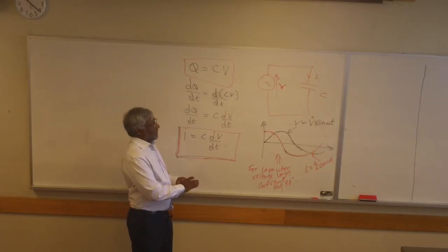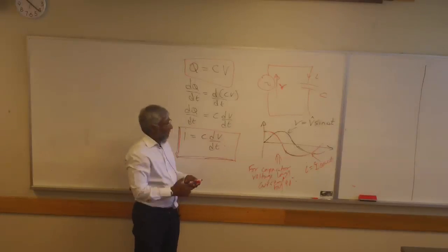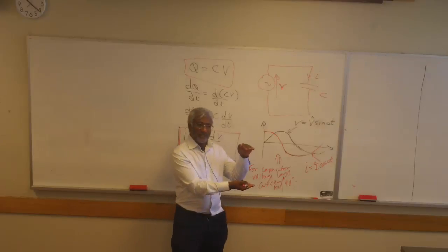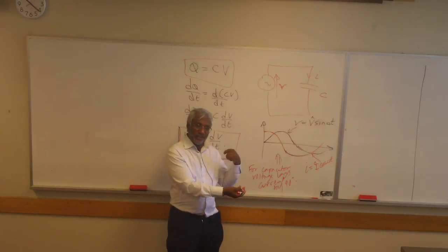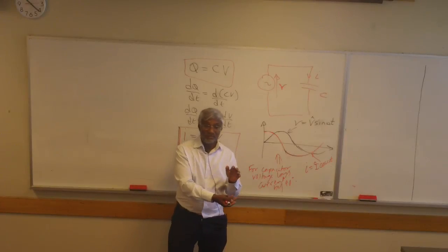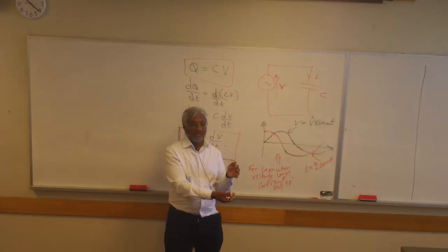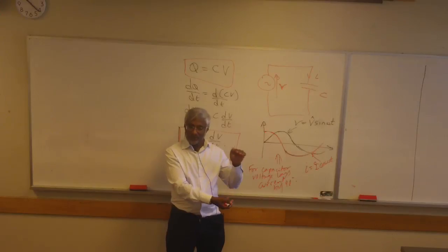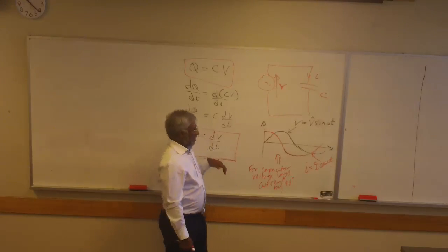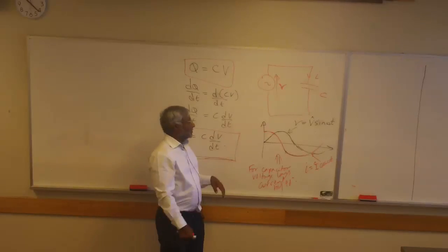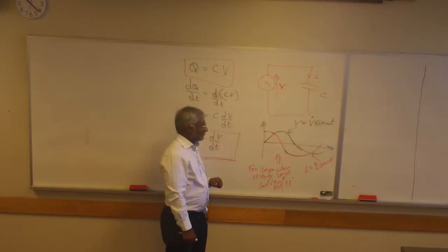That is obvious if you think about it. If you have a capacitor with voltage across it, then it means sometime in the past, current must have gone into it. So you don't have to read 25 books and worry about it. It is obvious that for a capacitor, current has to come first before it can be charged with voltage. So therefore, current leads. And for a sinusoidal situation, it leads by 90.